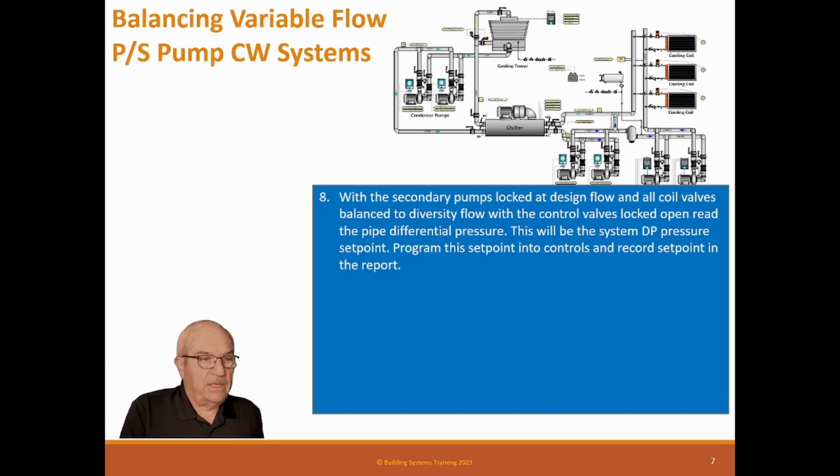I've seen some guys try to guess at what it is, and we ran out of water, so we guess again, then we run out of water and we guess again, trying to keep that automatic control operating. But the problem with the automatic control is you're balancing down, you're changing the pressure, and what's happening is the VFD is trying to keep that pressure so it's modulating. But remember, we're trying to do a block of flow to a block of flow.